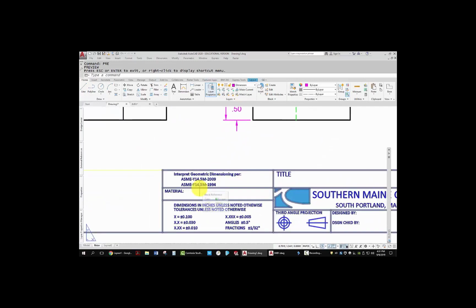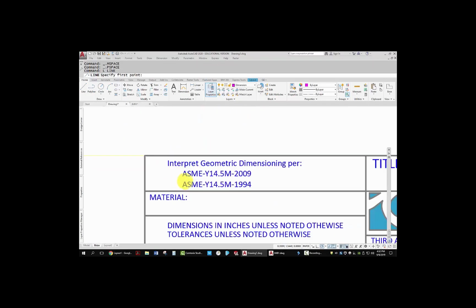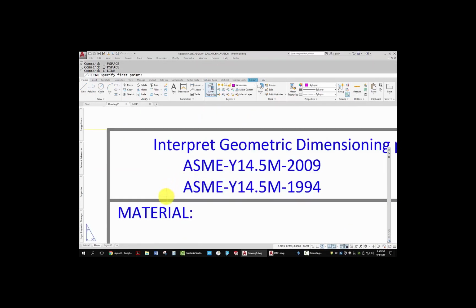By the way, I went back to paper space. I'm back in paper space so that I can do something with this title block, which I inserted into paper space. I'm going to just put a line right through. By the way, if I get too close down here, the line command starts over here at that end point. So here's a case where I don't want an object snap.